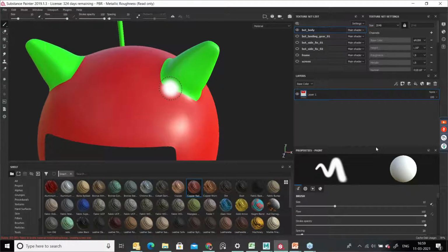But these bold colors are definitely really challenging for us. We'll try to smudge the texture. So how to do that? With the help of the clone tool we can do it. For cloning we have to use the options over here. I will show you that. With the help of cloning we can smudge the texture. For that, 6 is the shortcut key. Once you press 6, the clone tool becomes active.